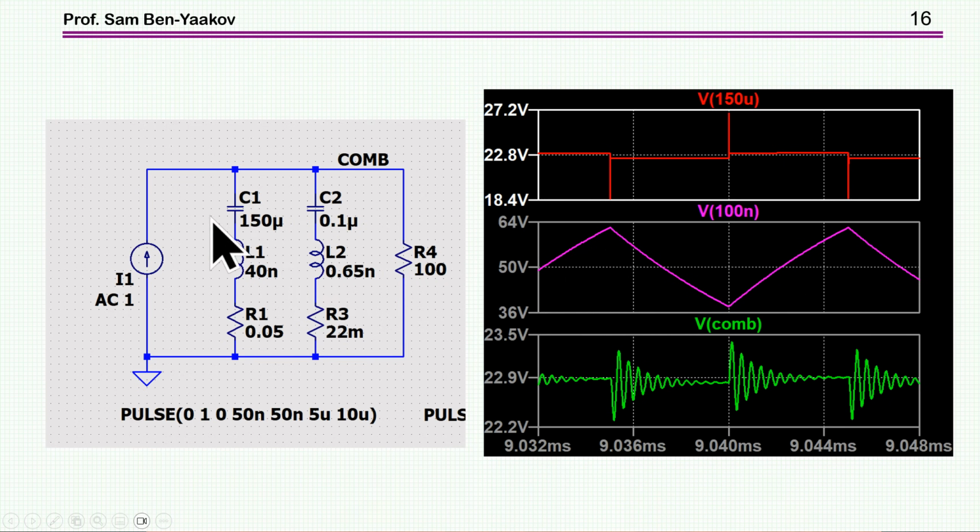Now, when you combine the two, the low frequency scale doesn't show us exactly this difference here. We show it also here, but we see now the oscillation due to the interaction between the inductance of the electrolytic capacitor and this low capacitance of the ceramic capacitor.